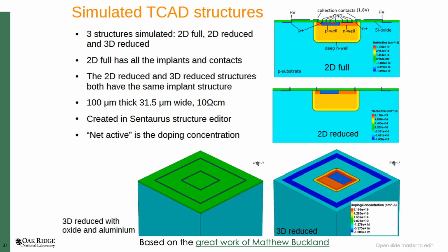So we just take care of having a big P well everywhere that we bias, having a backside that we bias, and the diode. The most important in that case was the size of the diode, the distance between the P well and that diode, and the thickness and resistivity of the substrate, because what we cared about was optimizing the field under there. That worked very well without having to put in all the detail of the CMOS.